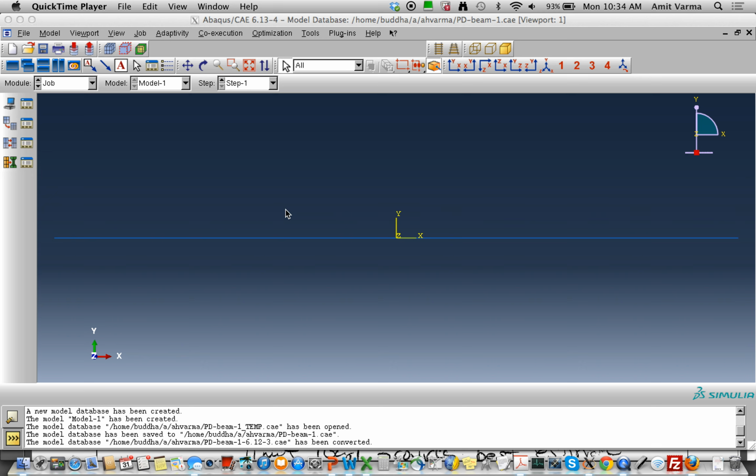And then we did what would be referred to as an event-to-event analysis. We went through doing sequentially elastic analysis by introducing plastic hinges. Since each hinge is elastic, perfectly plastic, I can do an event-to-event elastic analysis. So in the first analysis, we were able to calculate the elastic behavior, the corresponding deflections.